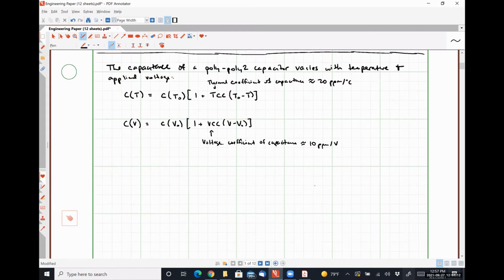So we saw when we did our examples using metal capacitors that, again, our bottom plate capacitance tended to be on the same order of magnitude as our intended capacitors, right? So how do you guys think we could potentially mitigate that?